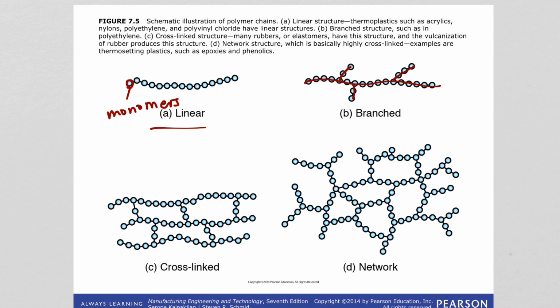If we try to pack those chains next to each other, there will be some resistance to having a highly dense packed structure because of those side chains, right? They will entangle with each other. Suppose there is another chain with a side chain here and here, and they will entangle. So those entanglements of branches make those chains difficult to move around, and this also strengthens the polymers, okay? Because if they cannot move around easily, you are increasing the resistance to deformation.